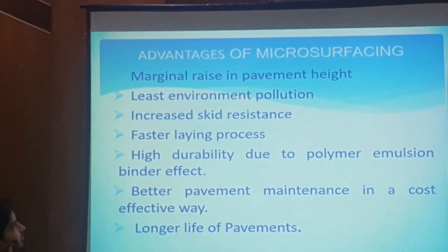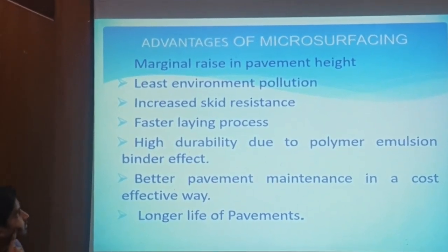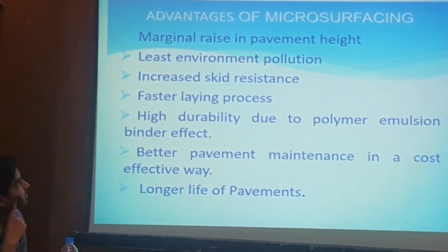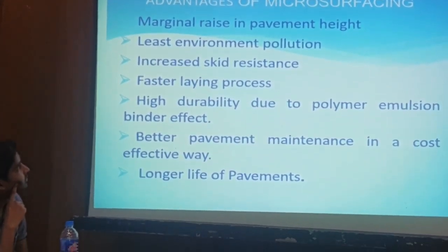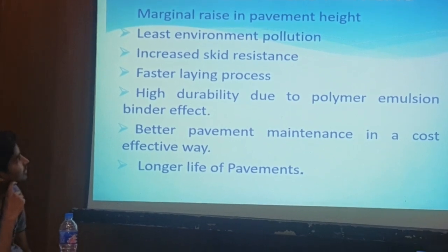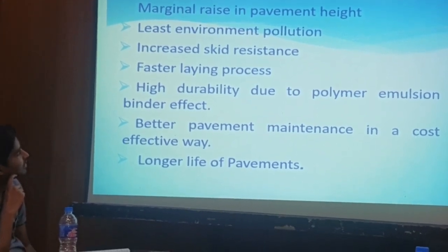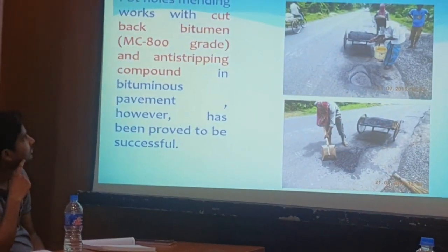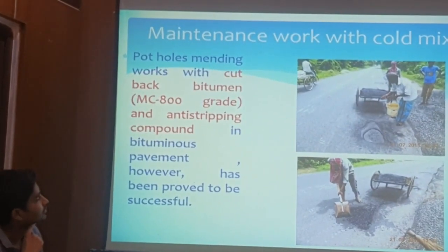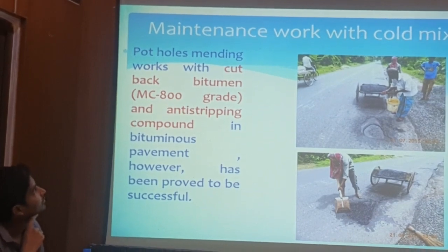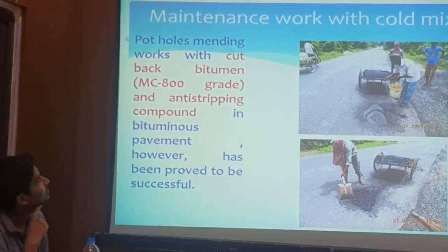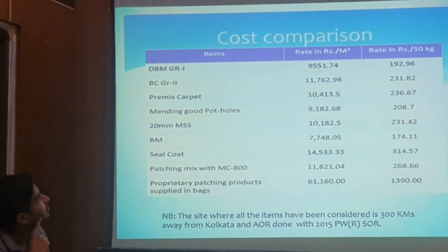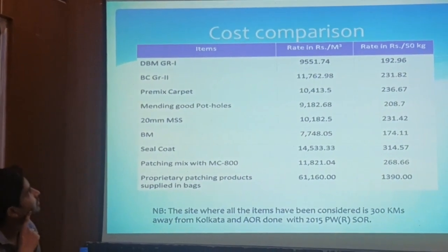Advantages: least environmental pollution, increased skid resistance, faster laying, it is very fast, and high durability due to the polymer emulsion modified binder, better pavement maintenance in a cost-effective way, and longer life of the pavement. These photographs I have already shown, maintenance work with the cold mix. These you have seen. We have also discussed the cost comparison.